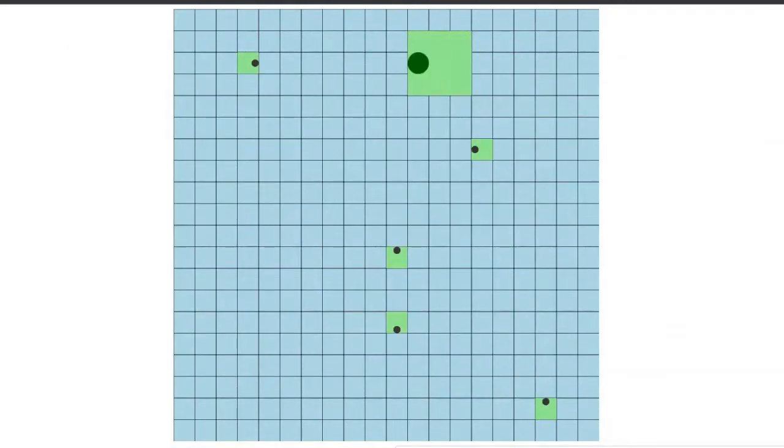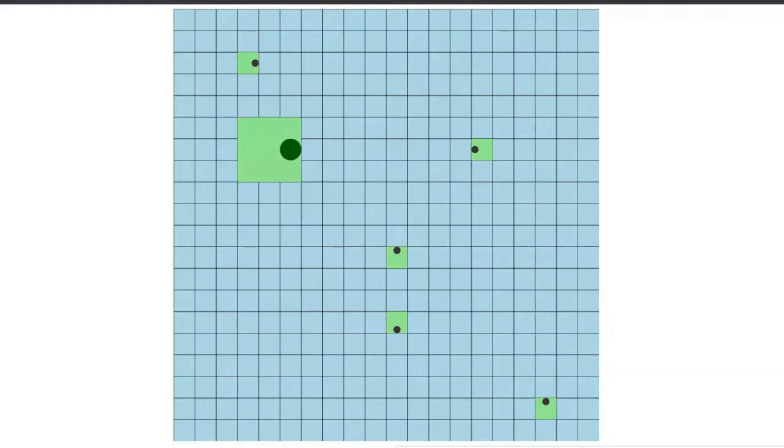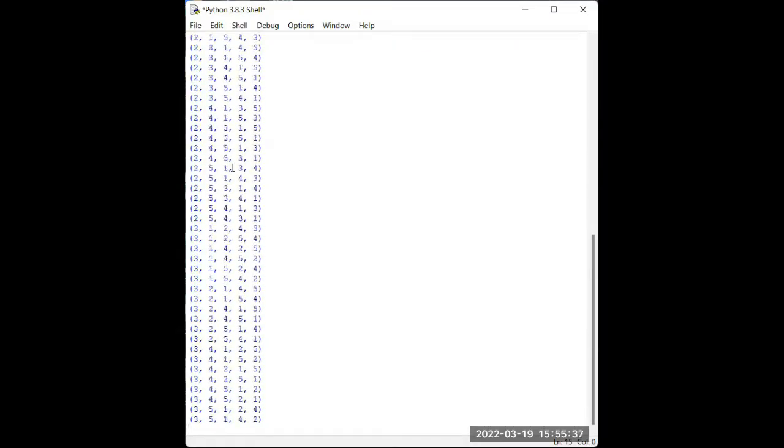A cost model was also assigned to give a higher penalty for turns to ensure that the robot will prefer moving in straight lines. To ensure that there is sufficient space between obstacles, we augmented the obstacles to a 3x3 virtual obstacle, and the robot will only pass through if there is space between the virtual obstacles. Turning radius is also an important consideration for us. Non-reachable obstacles will then be abandoned such that the algorithm can continue to operate smoothly.